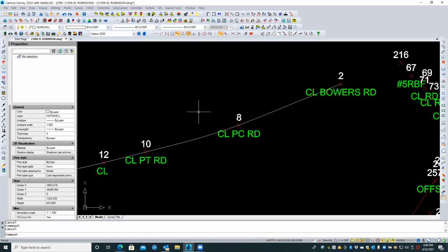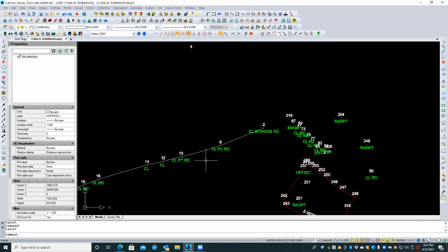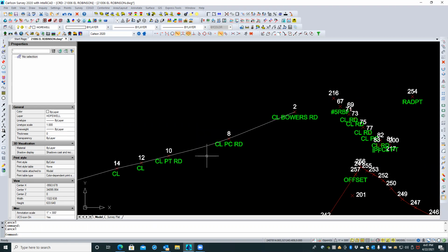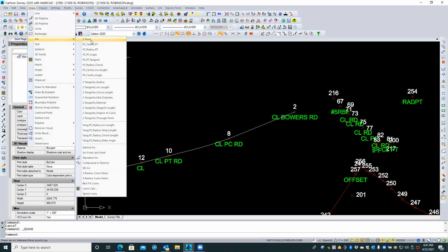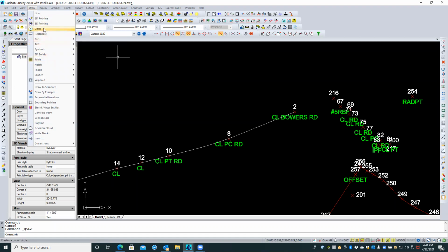All right, so 132. I'm thinking here I'm going to have to provide that number, so I would need like 135 if I'm going to allow that with field to finish. So anyway, we've saved this. It is tangent, and that's the way to do it by intersection, just as you said you should do in TerraModel. That would still work, and you could do that with the draw arc, the 2 tangents, and given that distance. You could also have done a circle.